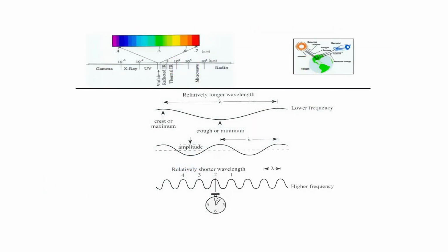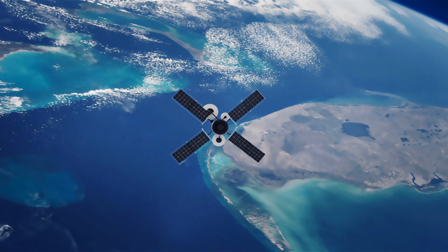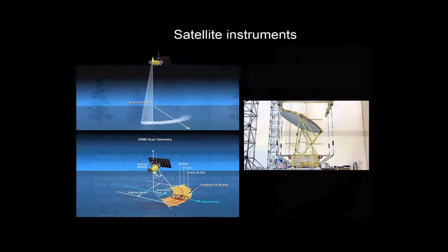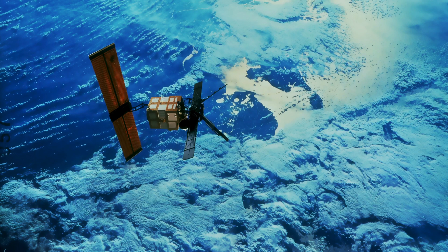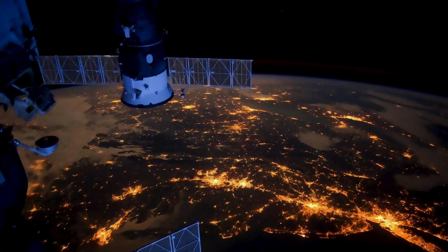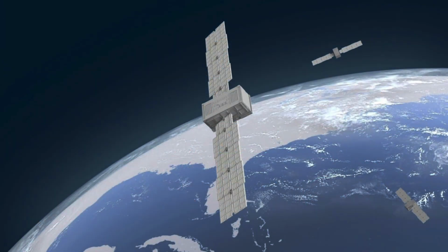On the other hand, when the sensors work in the regions of electromagnetic waves with frequencies between 10 to the power of 9 and 10 to the power of 12 Hz, it is called microwave remote sensing. This is highly useful as it provides observation of the Earth's surface regardless of day or night and atmospheric conditions. The radar is an active microwave remote sensing system which illuminates the terrain with electromagnetic energy, detects the scattered energy returning from the terrain and then records it as an image. Intensity of the radar return, for both aircraft or satellite based systems, depends upon the radar system properties and terrain properties.